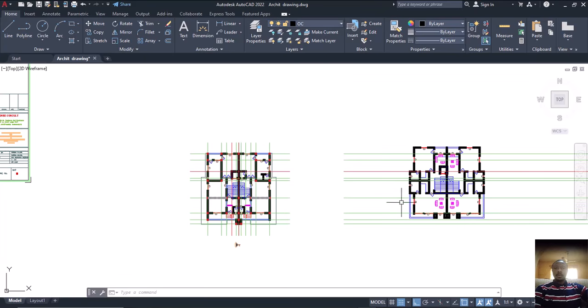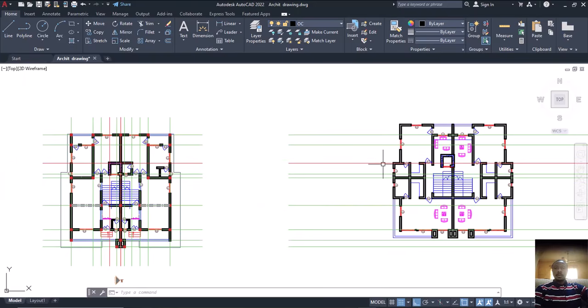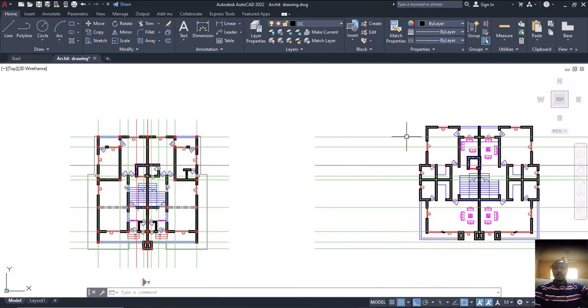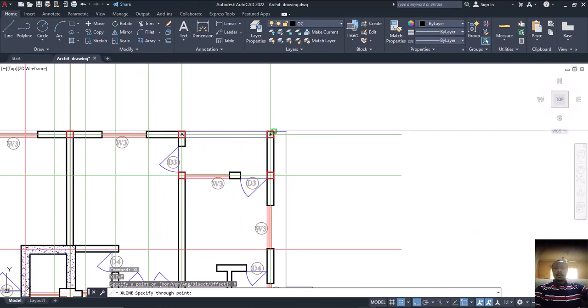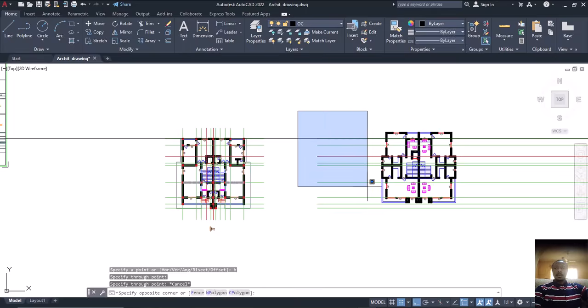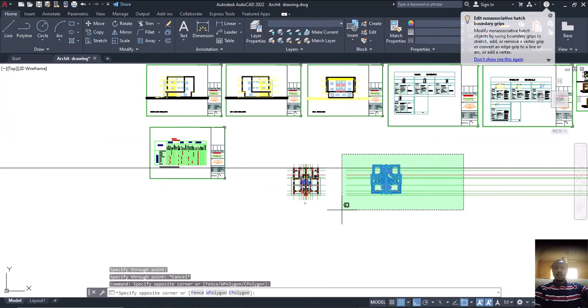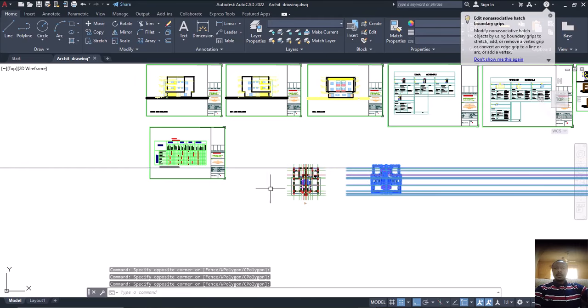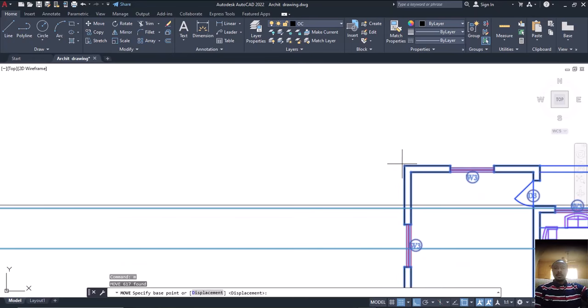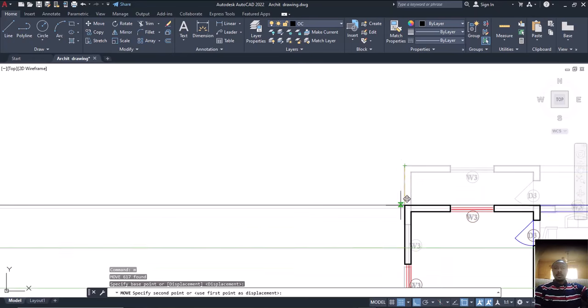So now, but first of all, we need to confirm and see if they are in the same place. Since I'll press my XL, enter, then H, enter, and put it here. Perfect. So since I've put it there, I have to select all of this like this, then press my shift key to select this one, and then press M, enter. M stands for moving from this point here to this point here.